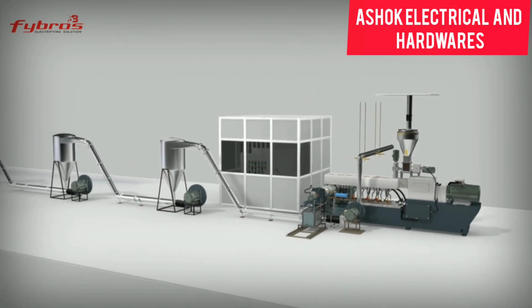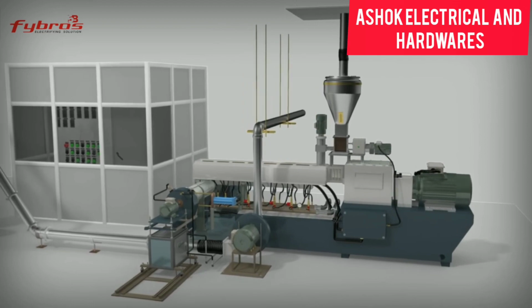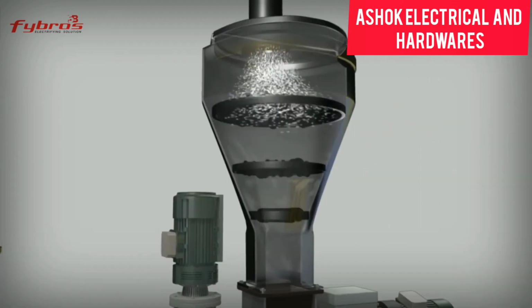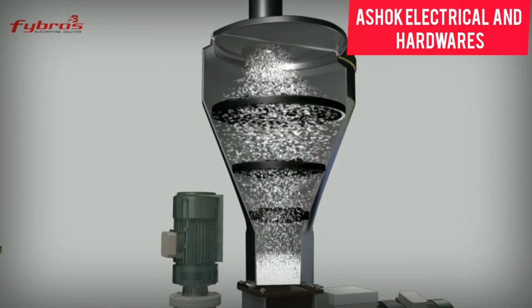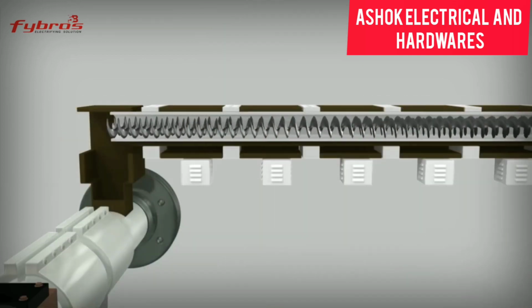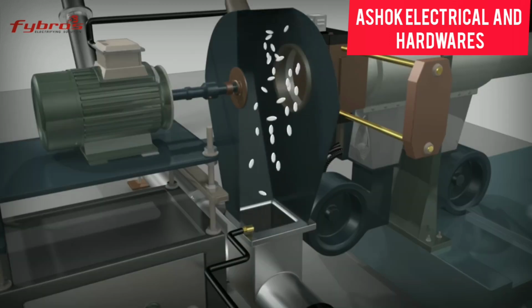The mixed PVC ingredients are fed into the extrusion process, where parameters, that is, barrel heating zones, temperatures and screw speed, are varied systematically and in random order to form the extrusion in the form of solid cords, which are then cut in the form of pellets. These heated granules are taken through the heated vents and cooled gradually.